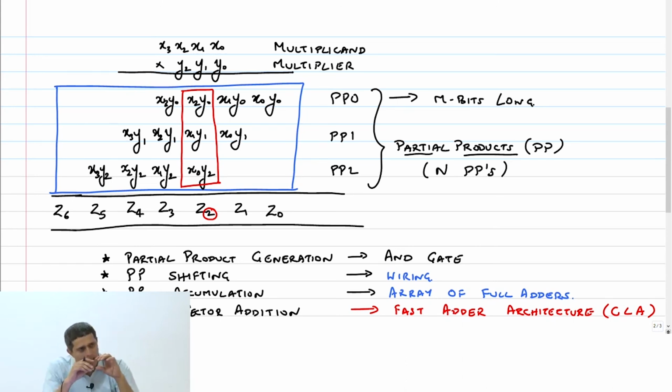You will find that the last stage just turns out to be a ripple adder. If you just put full adders, that last stage is just like a ripple adder. You can speed up that process by making that a faster, more intelligent adder, is all I am saying. One of the last rows in the array happens to be a ripple adder. Other things are not ripple adders. They are full adders, but it's not a ripple adder. Okay, we will see why.